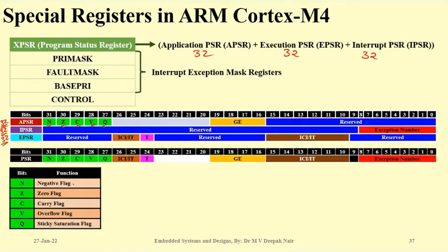If you can recall from the 8085, there were flags in the 8085 also, which used to tell us the status after an arithmetic instruction, what the output was, whether the output has zeros, or it has got some carries or auxiliary carry or overflow. So similarly here we have flag bits. APSR holds the data related to flags.